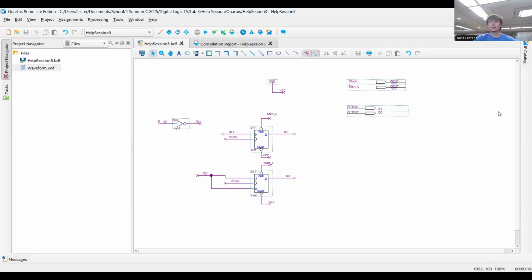It's pretty straightforward. When you have bigger counters, obviously you're going to have bigger logic. And always, like I said before, make sure that your state bits are outputs, because if you have inputs, that doesn't make much sense, and Quartus will give you an error. Now, if we think back to that example that I had before, right here, this one, where we have special counts, and I said you only need 3 states.